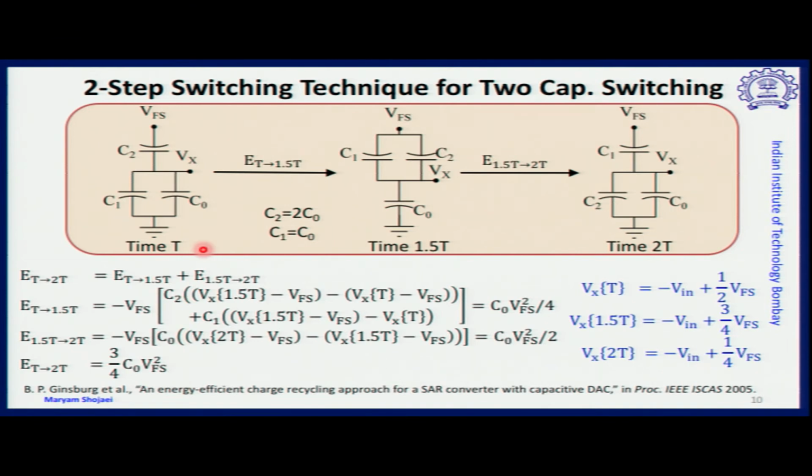If we don't go suddenly with single step two capacitor switching, but go step by step, we will be able to save energy. The reason is that we first reduce the voltage across the capacitor, for which the voltage has to go down finally, and therefore the energy loss will reduce.